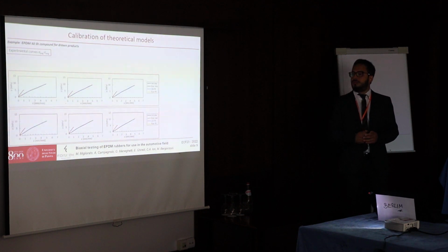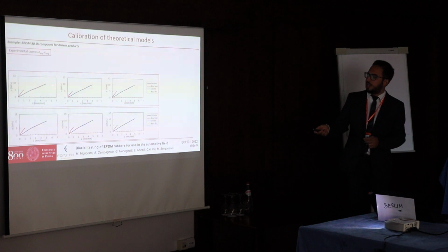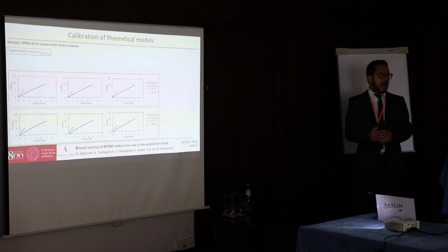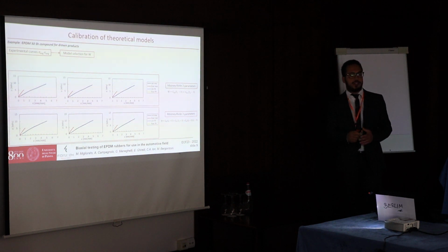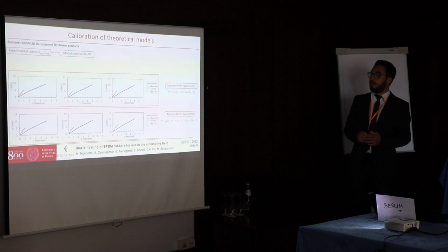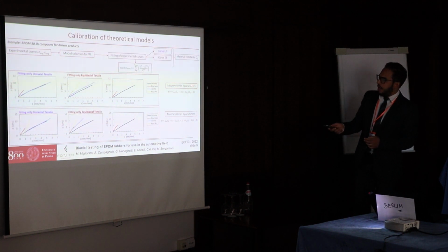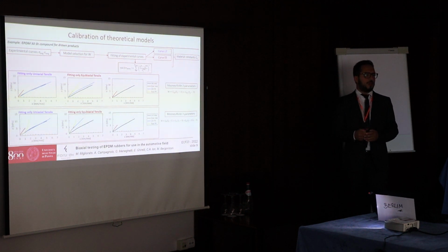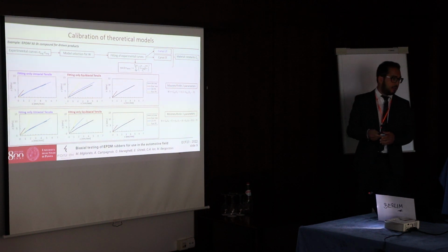Having the stress-strain curves under both uniaxial and equibiaxial loading, a theoretical model should be selected and fitted on the experimental results to be later adopted in finite element simulation. In this case, the models which better fitted the experimental results are those provided by Mooney-Rivlin with 2 or 3 parameters.